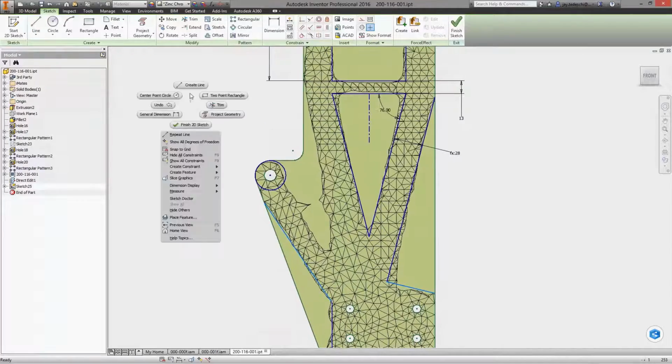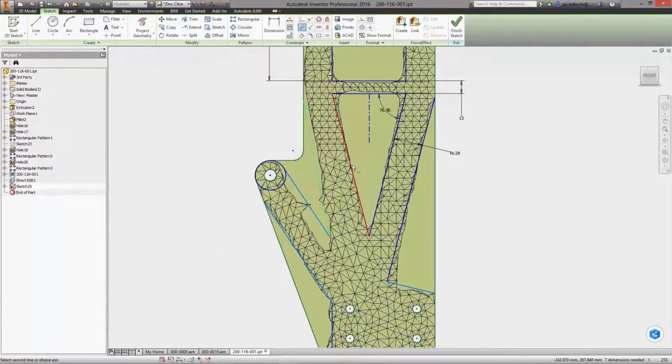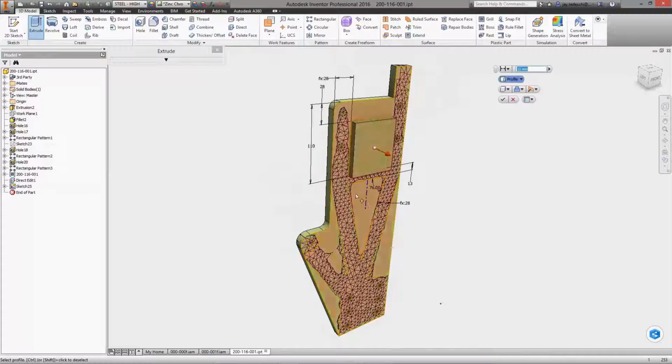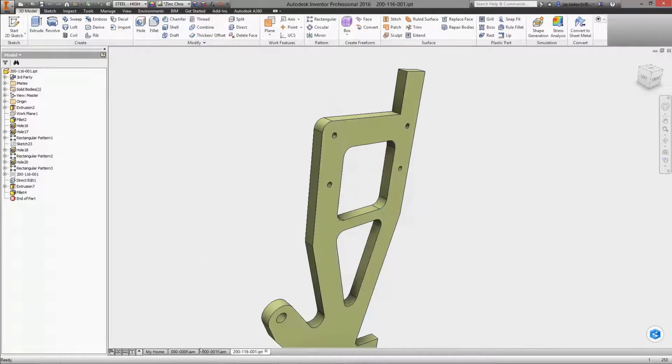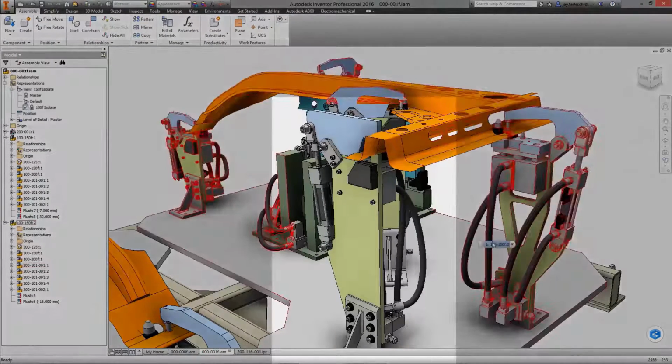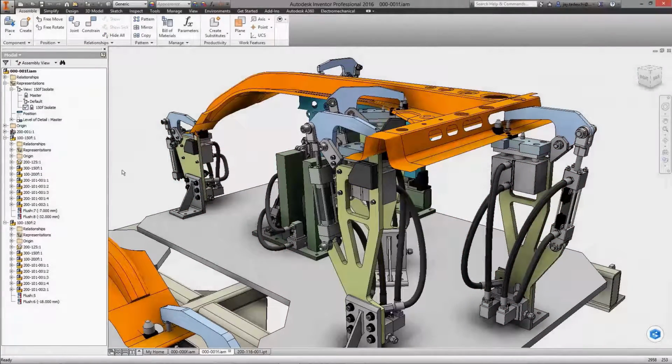So we then use that as a guide to go and remove material, with engineering judgment obviously, from those areas where we don't think that it's required, add some fillets and any other features that are required. And then obviously the most logical follow-on step would be to analyze this design separately, confirm that the typical and traditional analysis can validate the design as well, and then follow that up with any other requirements, such as structural analysis and then physical testing.